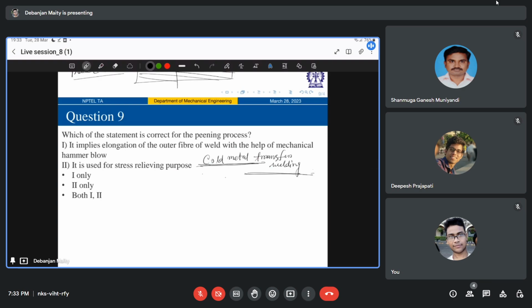So what I was saying, another approach can be a hot non-fusion process to eliminate the shrinkage associated with solidification of any kind of fusion zone, right? In hot non-fusion, there can still be some thermal contraction in any kind of heat affected zone that must be dealt with some tolerance or allowance, right? But the major source of residual stress will be the volume shrinkage upon solidification that must be eliminated.